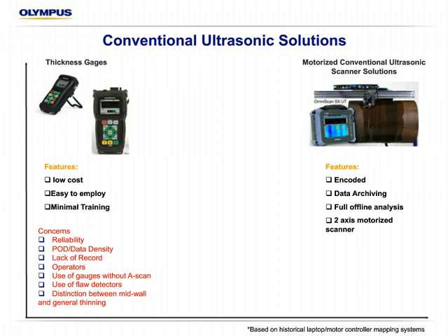But it's very good for general wall loss, to take a survey or after a pigging or guided wave survey to further assess and get an actual measurement of the wall loss. So a very small amount of data density is how we'll refer to it for the rest of the presentation. Somewhat of a record is able to be kept, but that's going to be either just a grid of readings or just a reading or a waveform save maybe. Otherwise it's mostly just a written report.